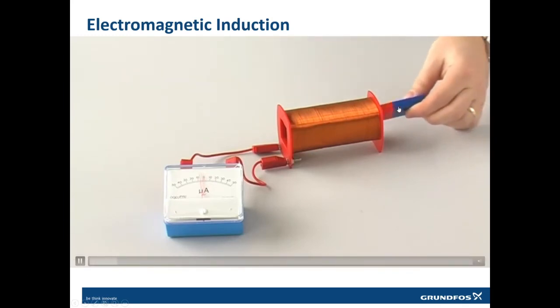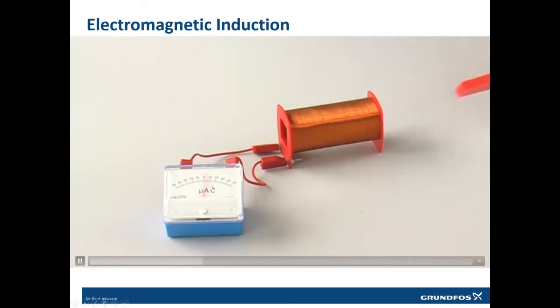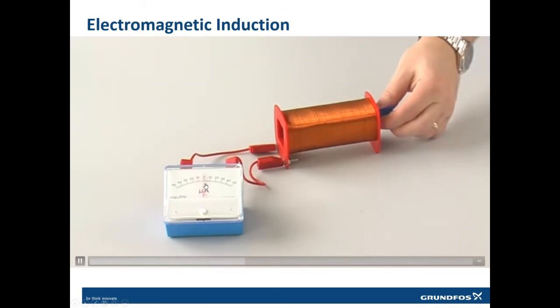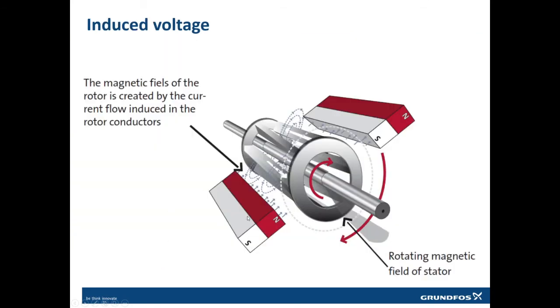So this concept is very, very simple. If you can see, this is a magnet, and if you are pushing it, it generates a current. This generated current will in return make another magnet. This is called induction, electromagnetic induction. So this is how it works. Just consider now that these are the electromagnets which are rotating around it very fast. This is the metallic bar. Once it rotates very fast, it will generate an electric current inside it. And that generated electric current, what will it do? It will make its own magnetic field, and that magnetic field is going to interact with it.